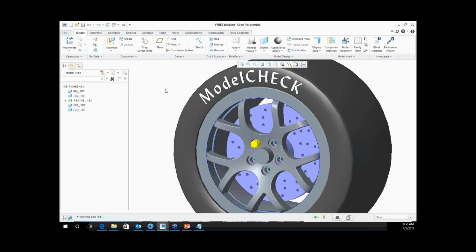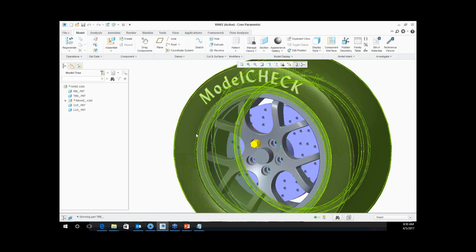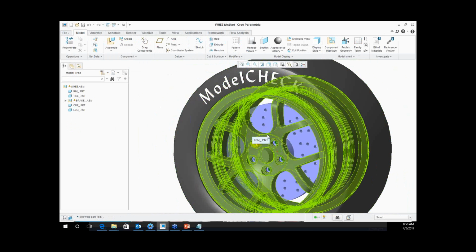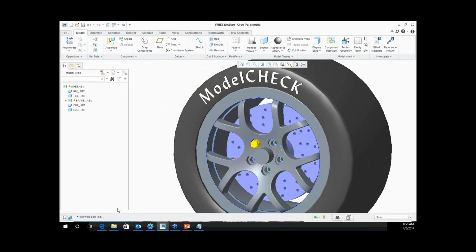And that means that radius there will reflect light slightly differently. And so in reality then, for Keyshot, you want to make sure that you round off as many sharp edges as you can, so that way you're getting a much more realistic light appearance off of your object, compared to if you just had perfectly sharp edges, and in that case it'll look more artificial or more fake. So for example, in this case, you'll notice a lot of these curves on the rim are all rounded off, right? Which is exactly what we want to do, right?